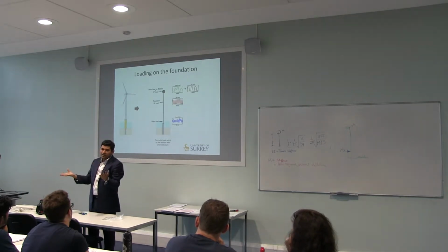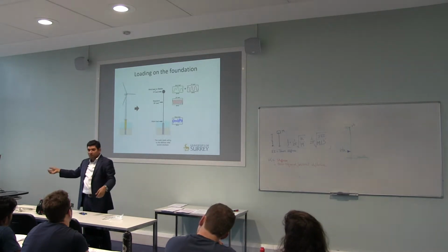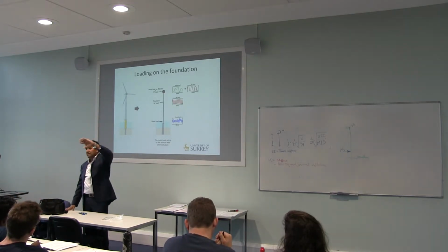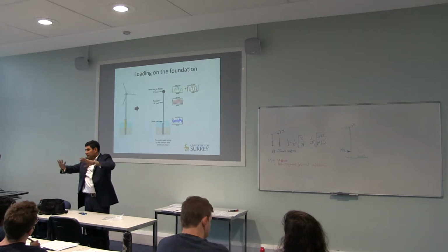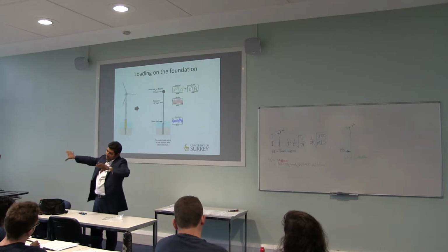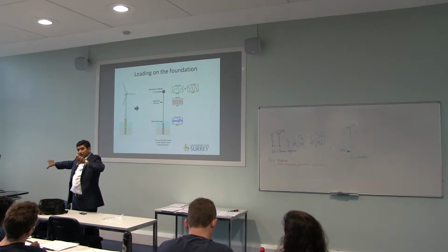There will always be misalignment, because you take this big blade and attach it there, so you can't align them perfectly, like a little bit of mass imbalance. Plus, the blade has got a shape, and that shape may not be perfect, so that causes a misalignment.